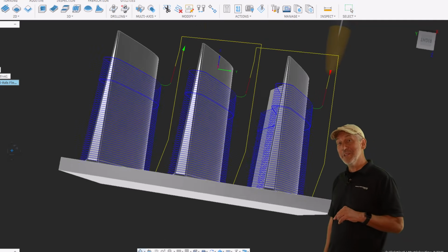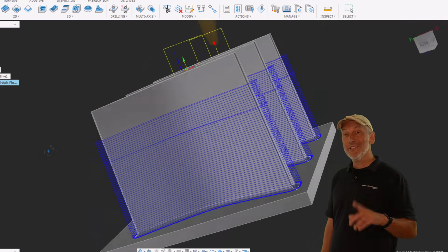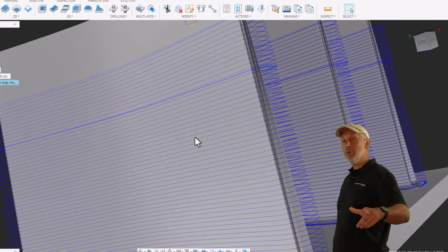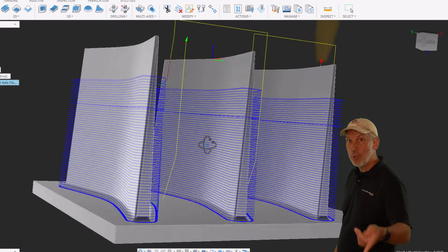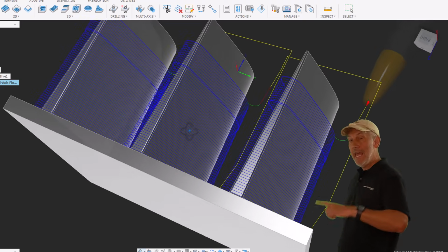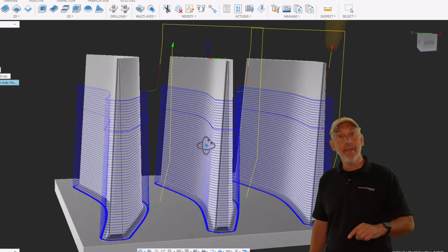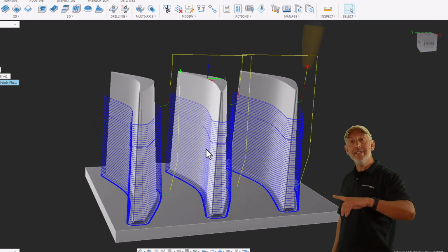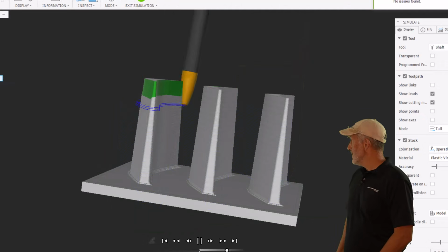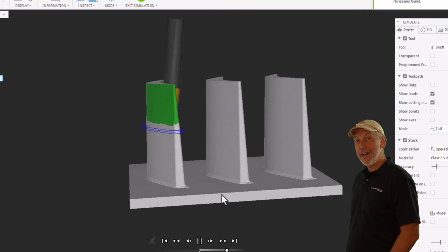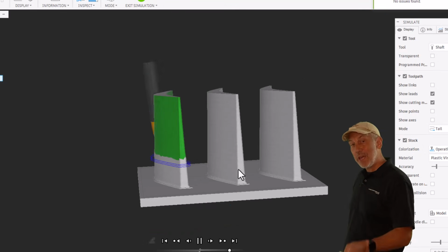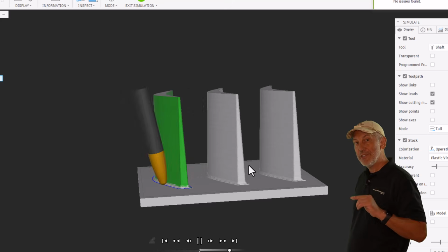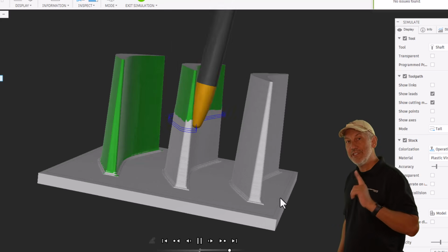Now that's a pretty looking toolpath. There weren't a lot of clicks. We used an oval form. It knows the dimensions because we downloaded the tool and we inputted them correctly. And now we got a very clean toolpath. Let's sim this and see what that looks like. Looks pretty nice. Cutting very well. And we're saving a lot of time because don't forget our step down is 40 thou versus 10 thou.